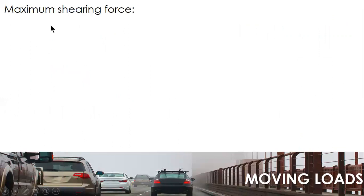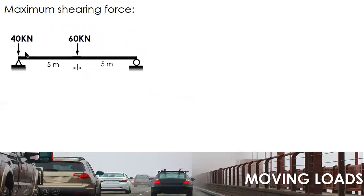Maximum shearing force. Remember the technique. You place the load over the support, leftmost or the rightmost load. Okay, so first setup 40 over the left support. The other setup is 60 kilonewton over the right support. And you solve for the reactions.